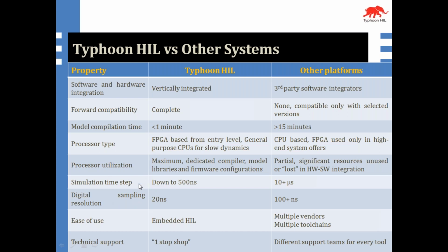Our simulation time step is down to 500 nanoseconds, but on other platforms it is 10 plus microseconds. For digital sampling resolution, Typhoon HIL is 20 nanoseconds, and on other platforms it is 100 plus nanoseconds. Here we also have embedded HIL, meaning hardware in loop, along with embedded Python 3.